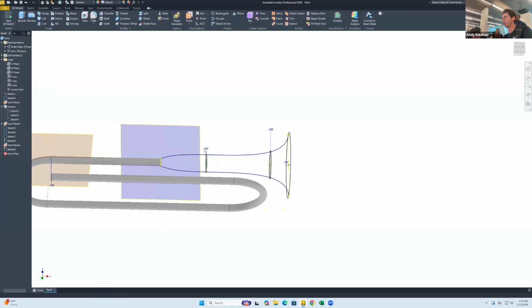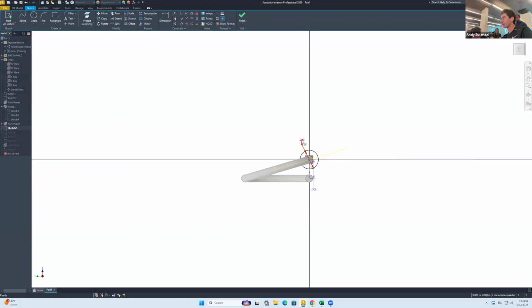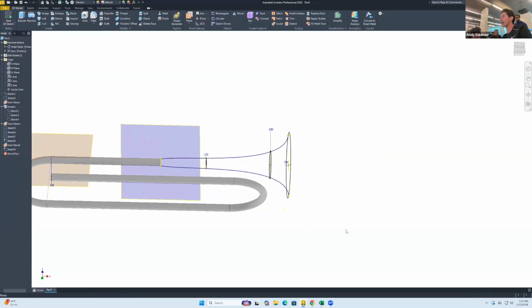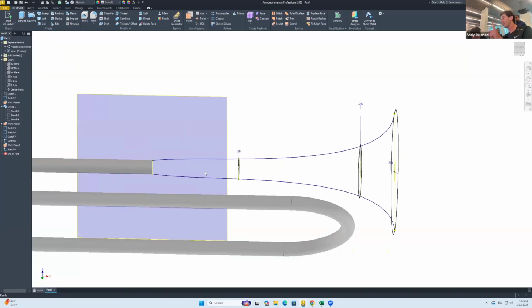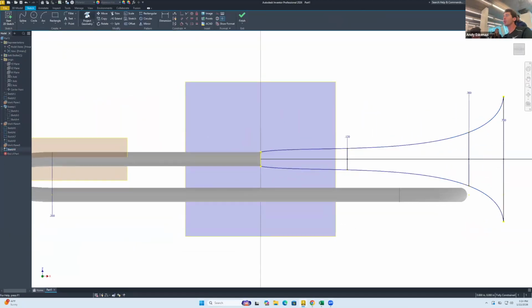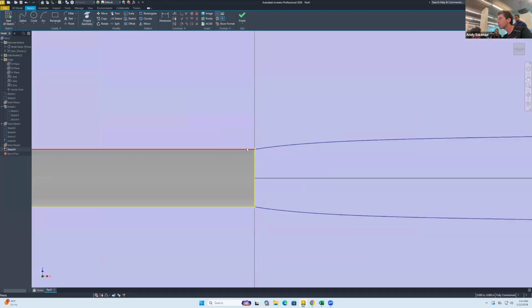In fact, let's go here, do sketch 5, edit, and we can make that a 0.1, a 0.12 as an example. And everything adjusts nicely from there. In fact, another thing that we could have done is if we go here to that sketch, we go to edit, we can do project geometry of these two lines. And let me just make these two just construction. Did they become construction? There we go.